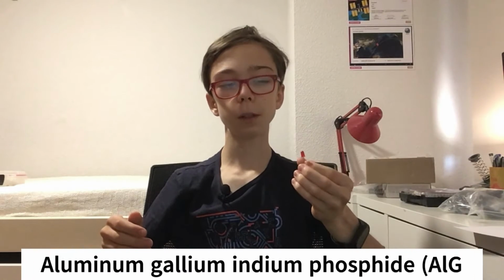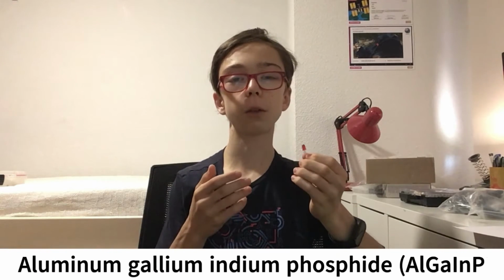Now, the color of the light depends, of course, on the wavelength, i.e. the energy, of the photons, which depends on how much energy it took to excite them out of the n-type semiconductor. This in turn depends on the material. So for red LEDs like this one, we usually use aluminum gallium indium phosphide. So it's not just that it has a red cover. Anyway, enough of the science class, let's get this working.